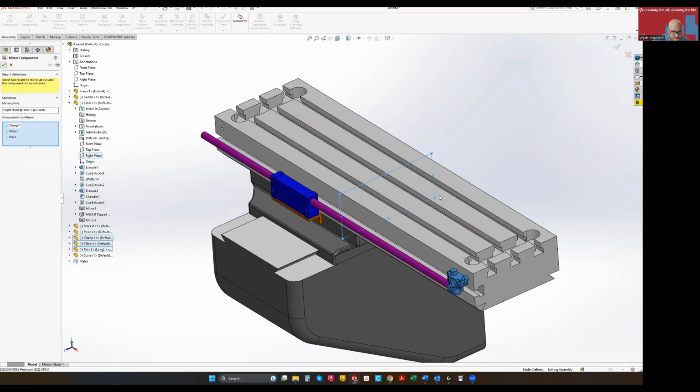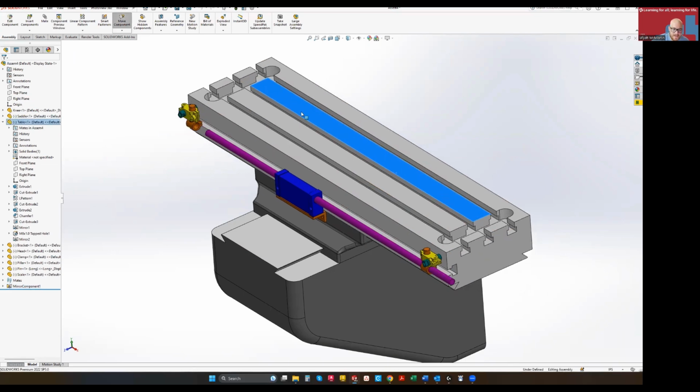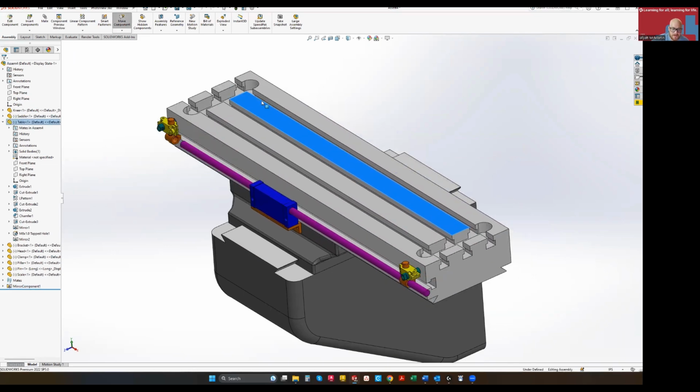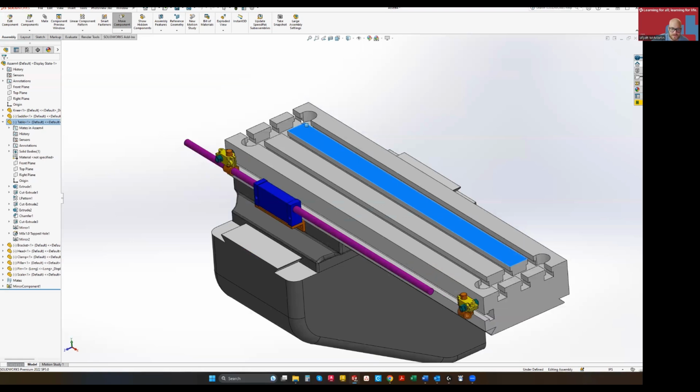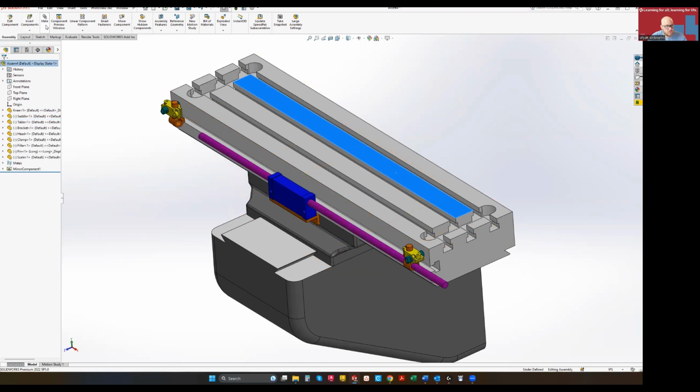And it has to be the table, it can't be the main assembly, because the table is going to move back and forth. So the mirroring of these components, we want these to be constrained on this side as well. So as the table moves, that plane is going to move, and the mirror feature of those parts is going to remain consistent where we want it. So now, last thing we've got to do is one final width mate with the scale.